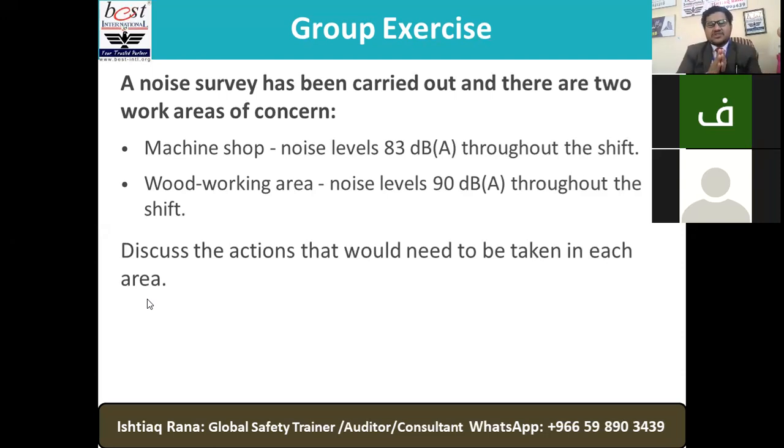If you believe engineering controls are not possible, we have done the maximum, and it is unavoidable, of course we can create some admin rules, like exposure time limits or putting warning signs. In our toolbox meetings we discuss which are the prohibited areas. We educate during the induction program, even our visitors, that you are not allowed to go to those areas. So we apply several administrative rules, and ultimately the last solution, PPE: ear defenders or earmuffs, earplugs, so we can reduce that impact.